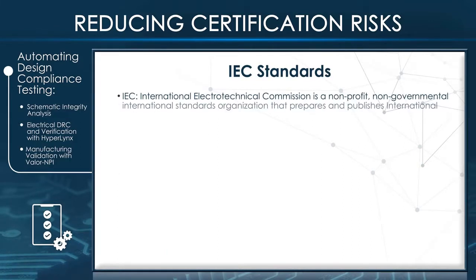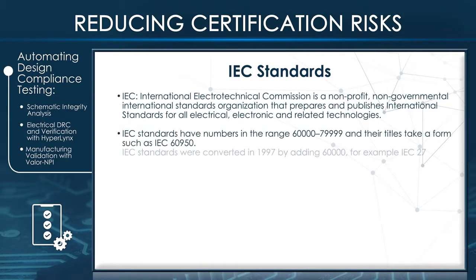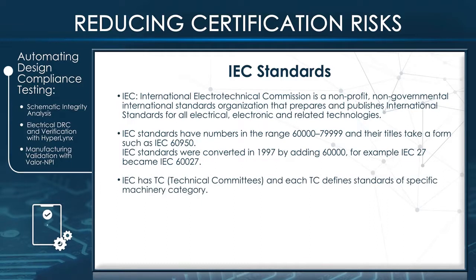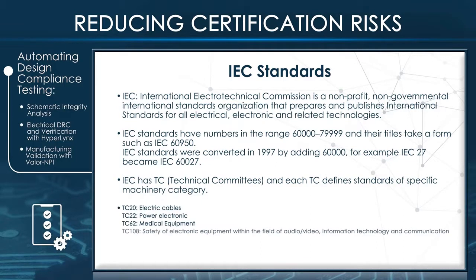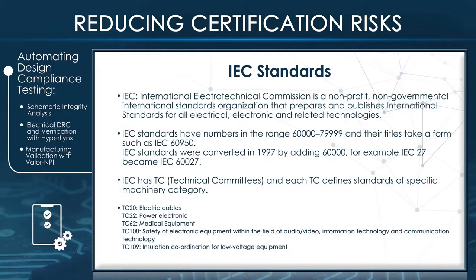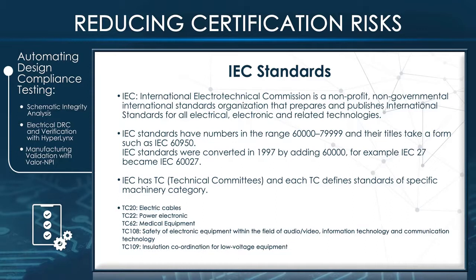And the way that customers and designers check for this today is they use IEC standards to validate the minimum creepage distance for their prototype board. There's different standards for power electronic equipment or medical equipment or IT equipment or electrical cables. So what we've done is we've actually automated this process and embedded these IEC standards into our HyperLynx DRCs. And we're going to show that in our demo today.